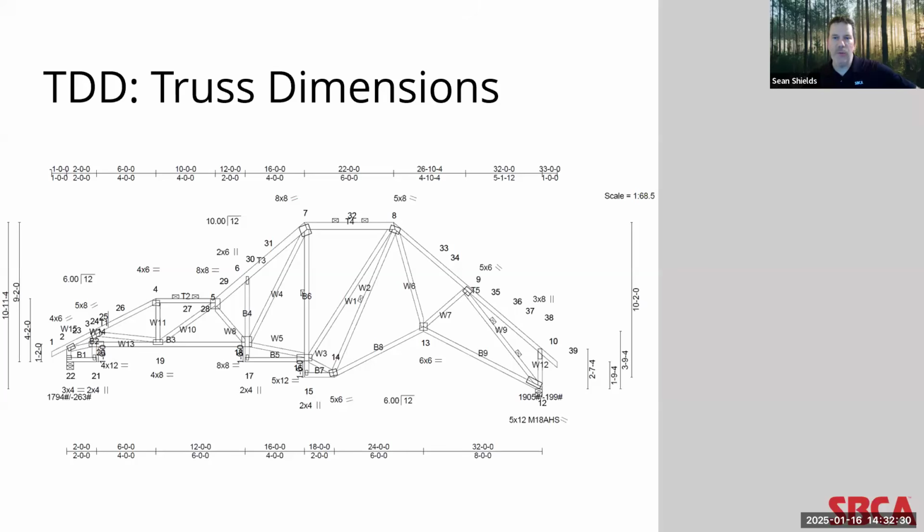On the left and right side of the truss design, you'll typically see 2 or sometimes even more measurements. The main measurement is the overall truss height from the peak of the truss to the bottom of the bottom chord at the bearing. Now, in some instances, this can help quickly determine or verify the overall height of the structure, for instance, but you do need to be careful because for complex trusses like the one on the screen, you end up having bearing heights that are not equal.